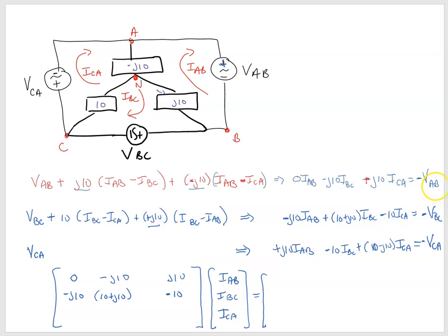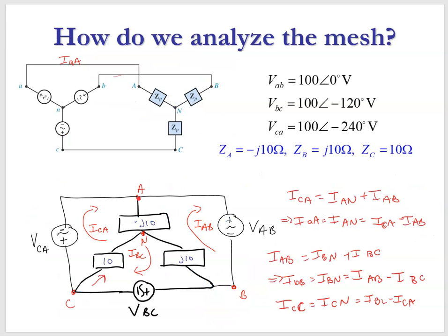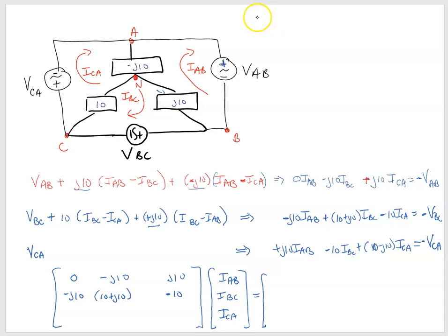And if you recall, we were given back here that our capital AB is the same as lowercase ab because there's no line resistance. So VAB is 100 angle 0 degrees. So we probably should write that up there. Sorry to go wacky there for a minute. Okay, so this is negative of that, so we can just write in negative 100.